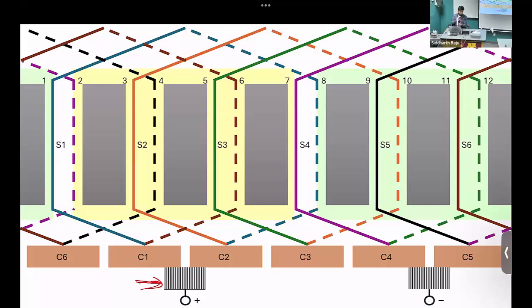And our coil is located in this direction like this. So it has rotated from some angle, say 85 degrees, to this position, 90 degrees. That's when the short is happening. So this is absolutely fine because the flux is going to be maximum, but EMF is d phi by dt, right? So the EMF across the coil is 0. So there is no issue shorting this coil at this point, right? Even if it's at an angle slightly behind, as long as the EMF is small enough, it's okay shorting it because the brushes themselves have a significant amount of resistance, so you won't actually be shorting copper wire, right?